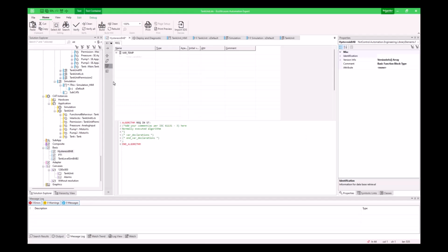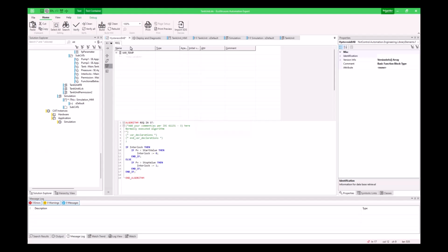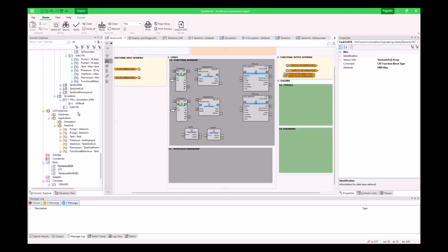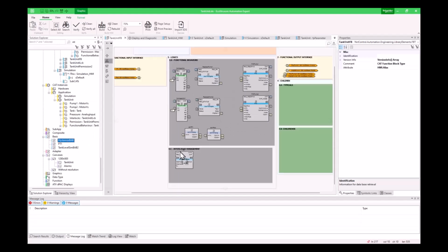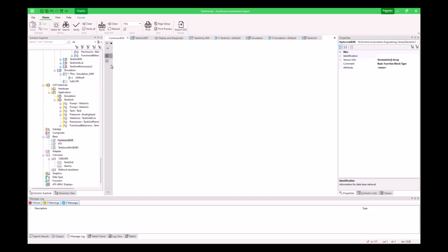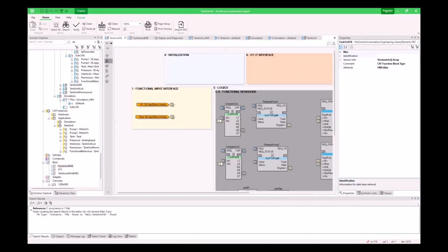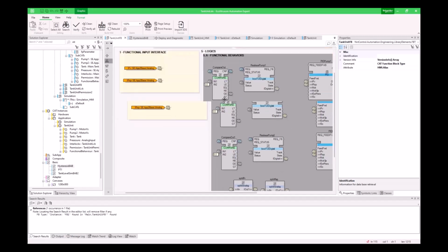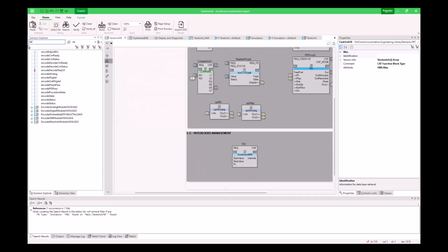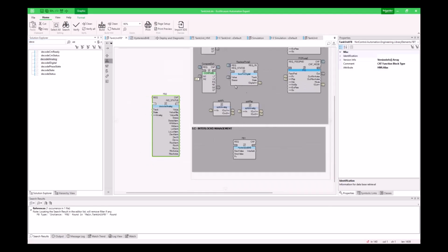The logic is simple. If the interlock output is active, reset it when the actual pressure falls below start pump 2. If the actual pressure rises above stop pump 2, the pump is no longer needed and is locked. To get the actual pressure, I use a decode analog block and another split analog block.